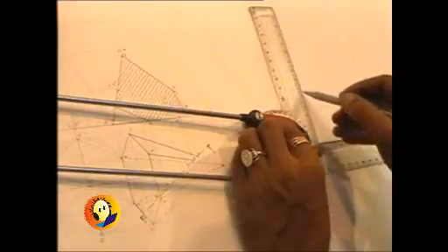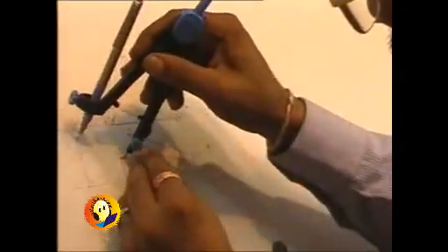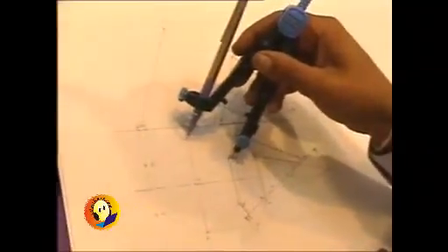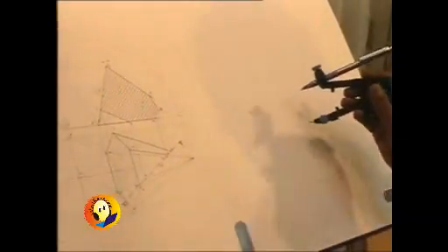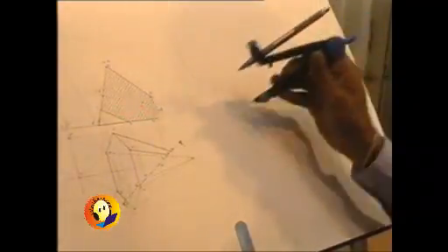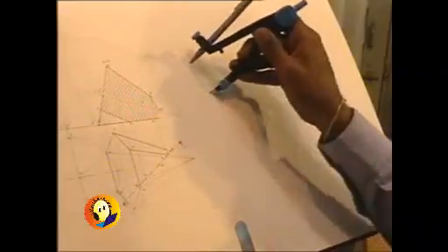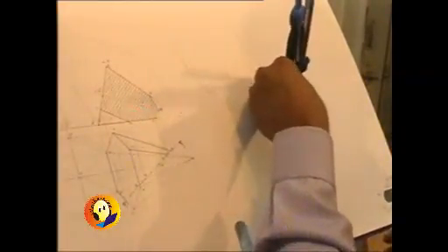Now generally we will prefer to have the symmetric development, so I am drawing the vertical line first, and I am supposed to draw in all 6 triangles such that the base of each triangle is measuring 40 millimeters, and 40 millimeters is nothing but the side of the base hexagon. Take that 40 millimeters distance, and then onto this particular development from the vertical line that we have drawn, mark 3 distances on left as well as right. So 3 on the left and 3 on the right, so that the development in this case will be the symmetric one. So there will be in all 6 triangles which will appear in this view, which we are required to draw now.